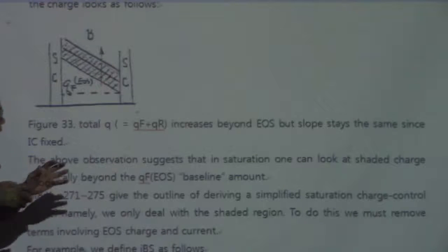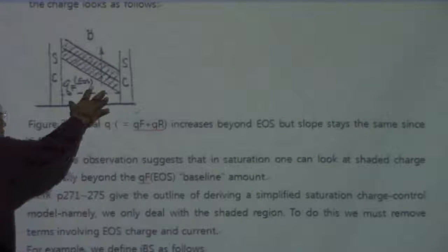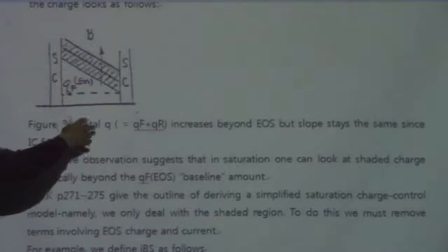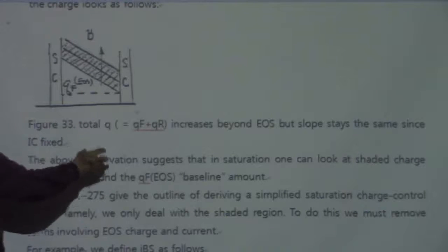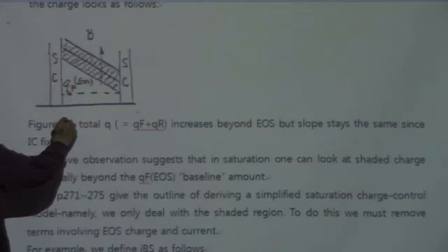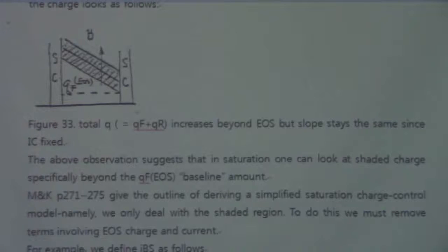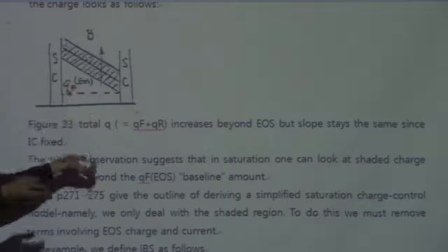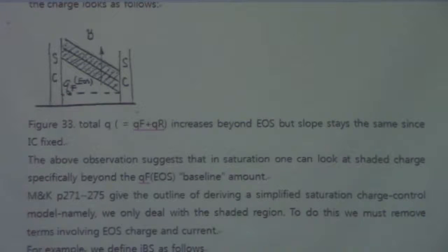So if you just reverse the bias on this system for the switching, then this bipolar transistor is not going to work until all the stored charges are eliminated from this.